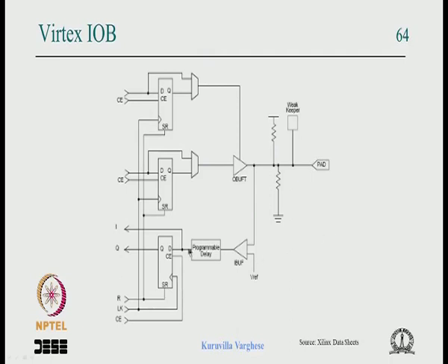In this we have seen the IO block. Essentially it's a tri-state buffer which allows an output path, an input path, and a tri-state path. Okay, and this can be combinational. So as I said, there are FPGA wires here, so the output can come directly or through a flip flop, so it can get synchronized and go out.